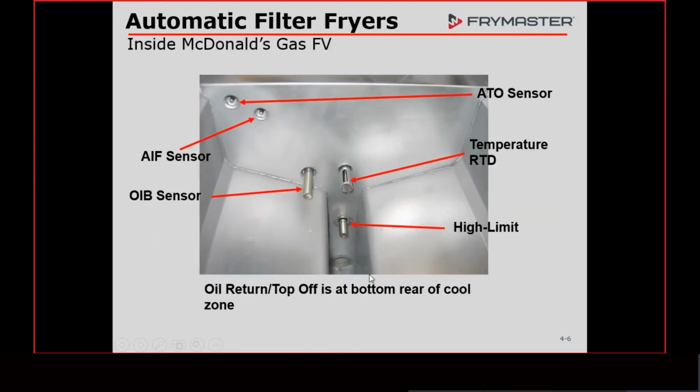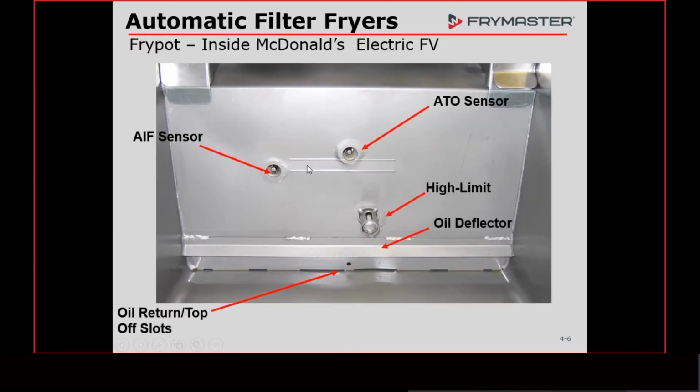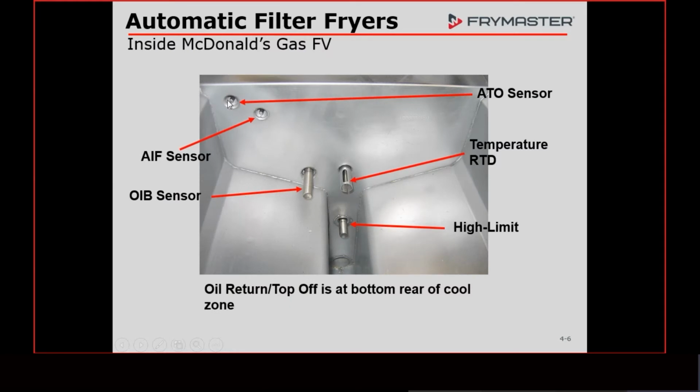On the Filter Quick fryers, not the Love fryers that McDonald's has, but on the Filter Quick, we can check the temperature, and I'll show you that in another slide, but I want to show it here too. We can check the temperature of this probe, the ATO probe, the AIF probe, or the temperature probe.